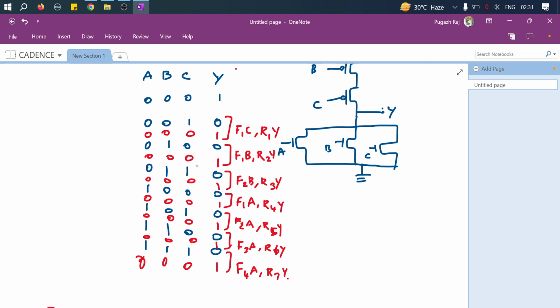These are the inputs inserted. Why? Because we need either a falling edge or a rising edge for each step, so we can calculate the delay for every step. These inputs can be written in different ways also. Now I have included zeros in between, so that in the first stage, the output goes from 0 to 1. See, I am giving an arrow mark here. It is a rising edge of the output.